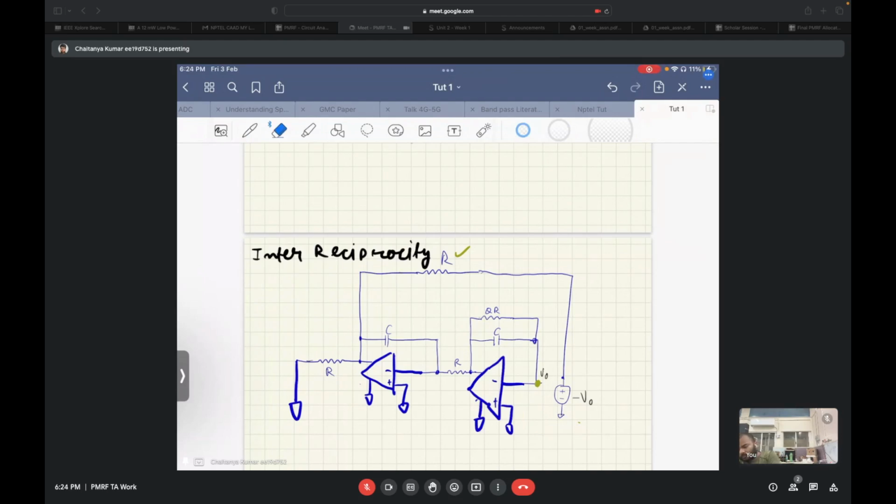Same thing we will do for the voltage controlled voltage source also. So the voltage controlled voltage source will transform into a current controlled current source. So now let's see how we will transform it. Again, this is the one that we need to transform. If we increase this voltage, this will reduce. So now we need to put a current sensing over here.